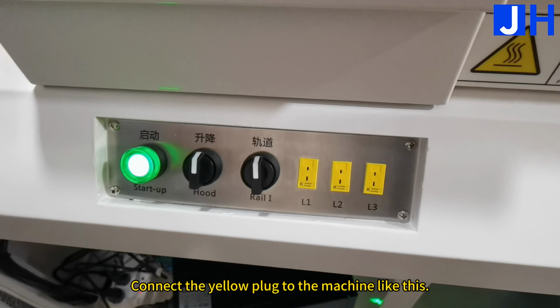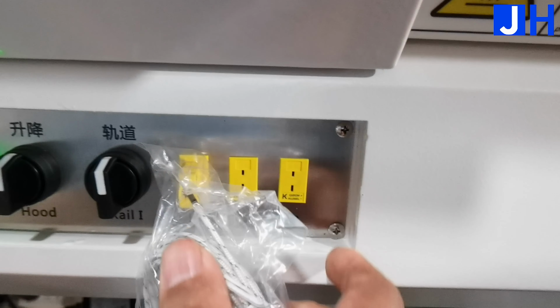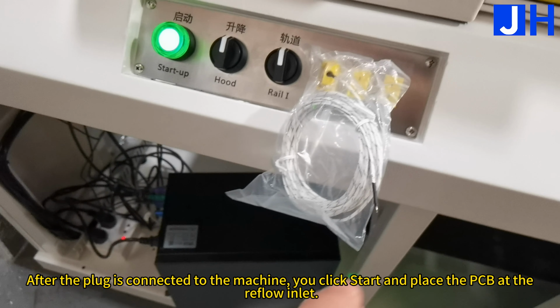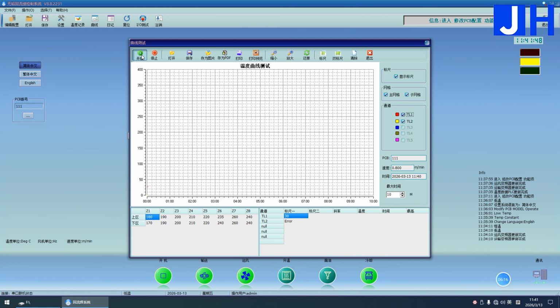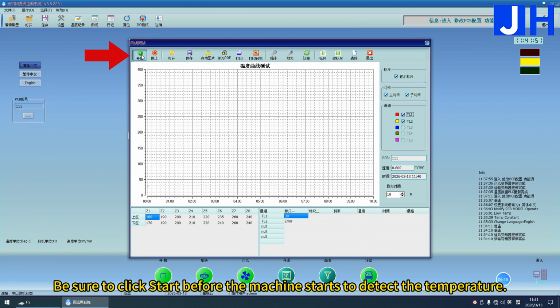Connect the yellow plug to the machine like this. After the plug is connected to the machine, you click Start and place the PCB at the reflow inlet. Be sure to click Start before the machine starts to detect the temperature.